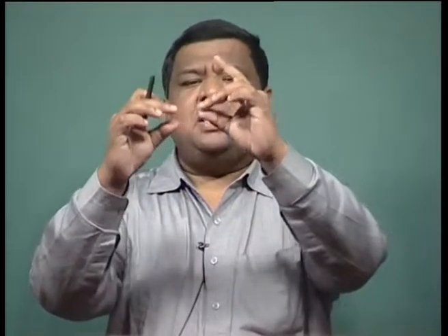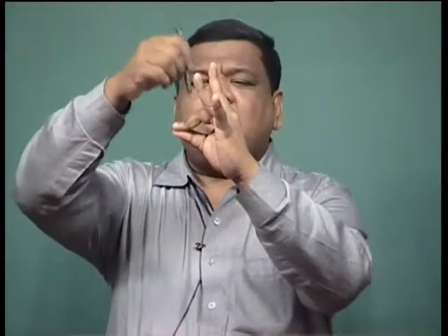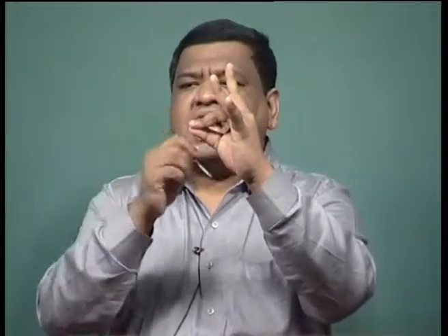So, if there is any crack like this and a compressive stress is acting on both sides, then what will happen? These crack tips will be closed. So, this crack tip cannot go further, and therefore, fracture toughness is improved. Fracture toughness is a measure of the crack propagation ability in the material. If the crack propagation ability is reduced, then your fracture toughness is increased.